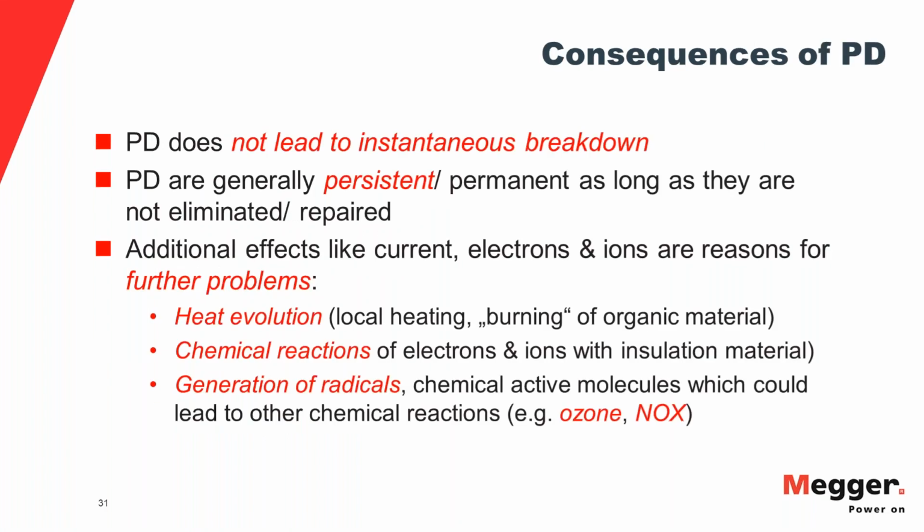And then what's the consequence of PD? The problem here is if you do a VLF test and a VLF test only, and that has been established for years. This is no news. Some people run around and try to say, oh, VLF testing is not finding all the faults. Well, that was clear almost from the beginning, a few years into VLF testing.